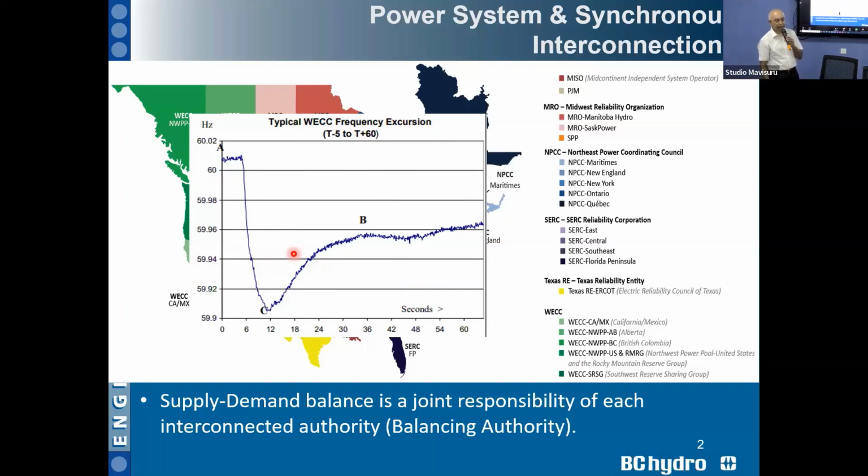Yeah, I know in Sri Lanka it's 4%. It's fair because you are having a 50 hertz signal, whereas we are having a 60 hertz signal. Our generator is 5%. So no unit in whatsoever condition will operate at other than 5% droop. Every machine in the system will operate on 5% droop. No 2%, no less percentage.